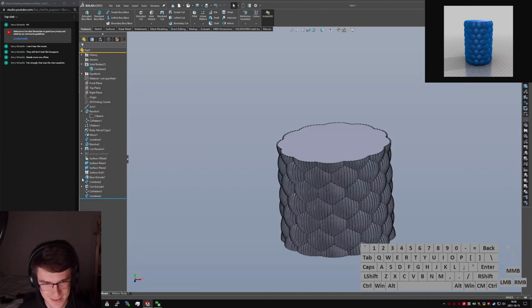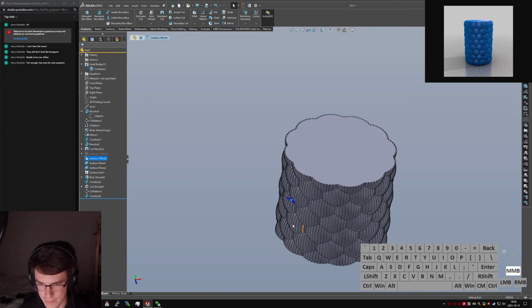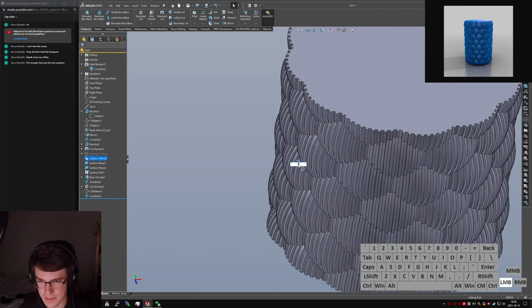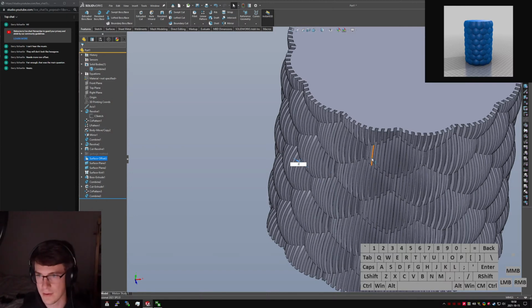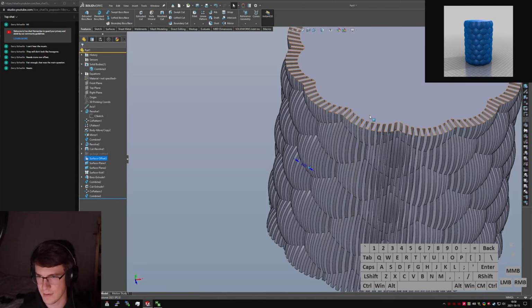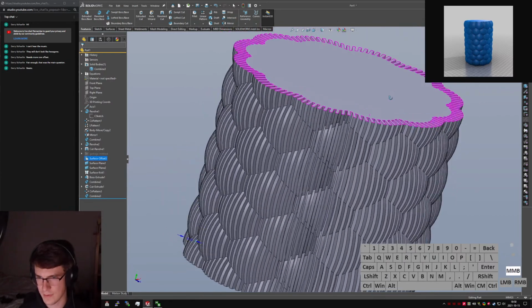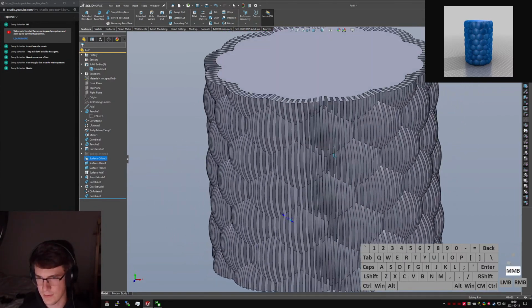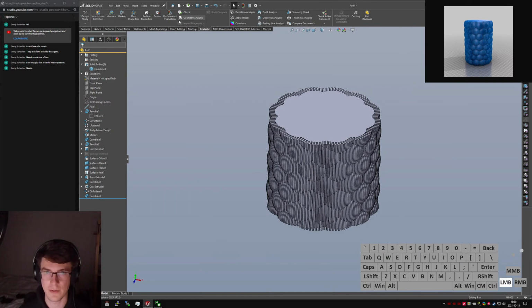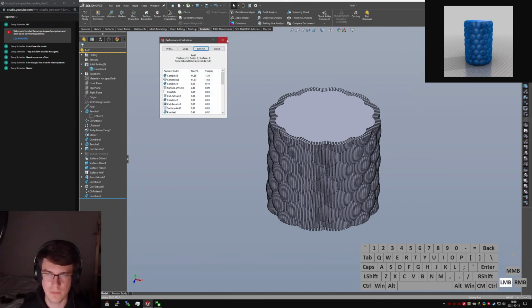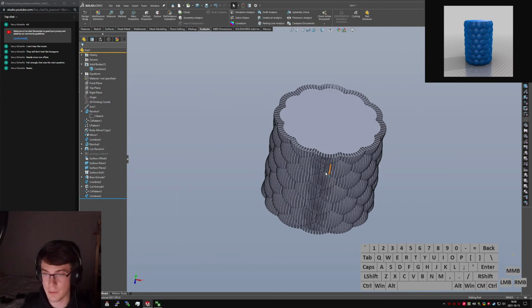Much better. So I should have, through this surface offset, I should be able to make this variable depth. So I can hit 2 here, and then through many minutes of rebuilding. Let's see how deep I can make that. Will 5 millimeters work? Or is it going to throw a fit? Quick evaluation of performance. 4-second rebuild. Doing a lot better than we were.